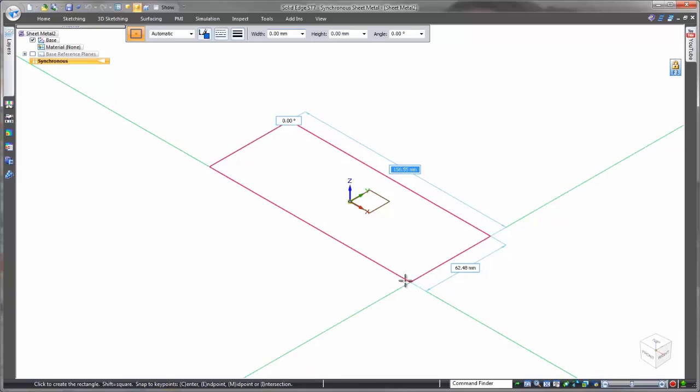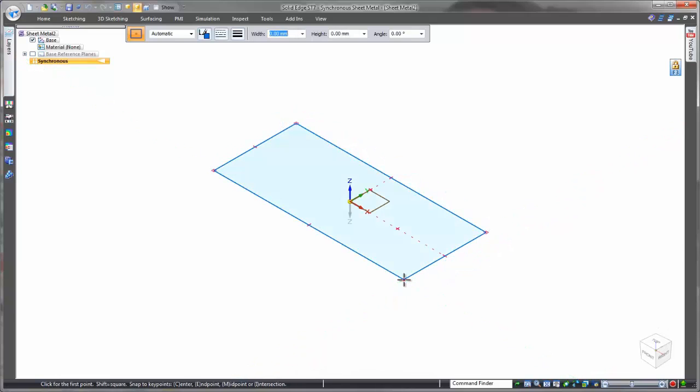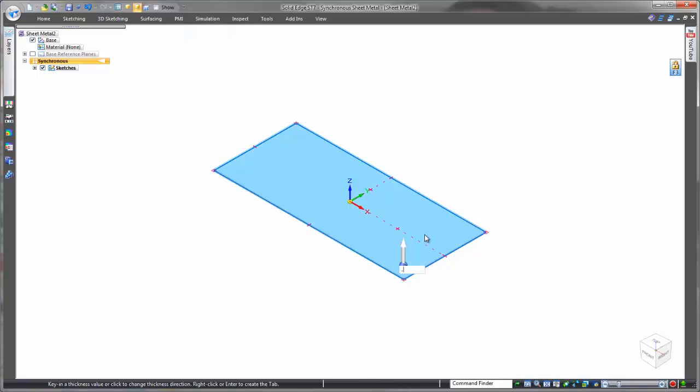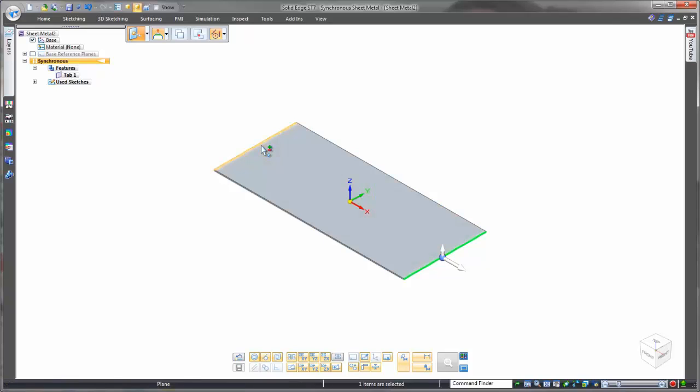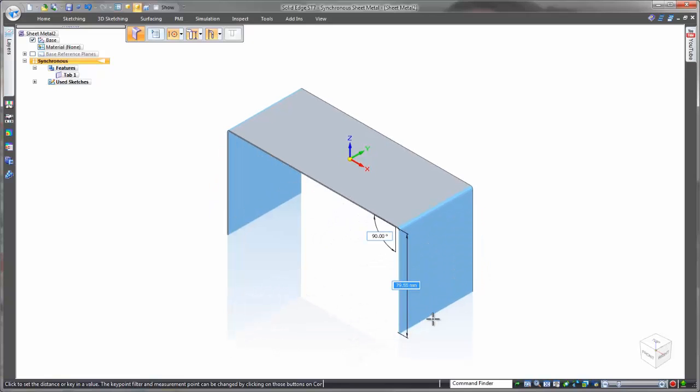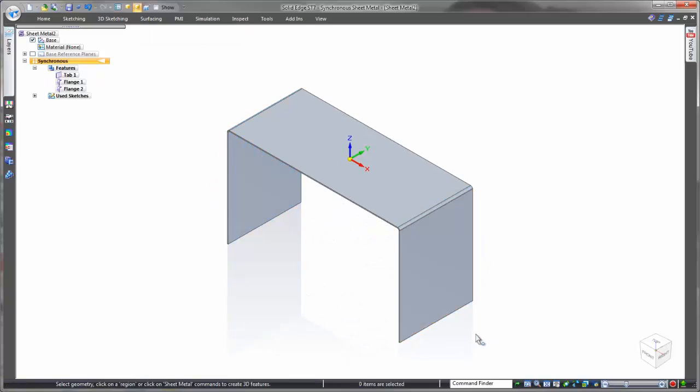I've just been briefed on a new spring clip that we need. So let's throw this design concept down. So we create this model, please pay attention to how much we work with our geometry on screen rather than clicking into commands the way it should be. By selecting more than one thickness face, we can create multiple flanges at one time.